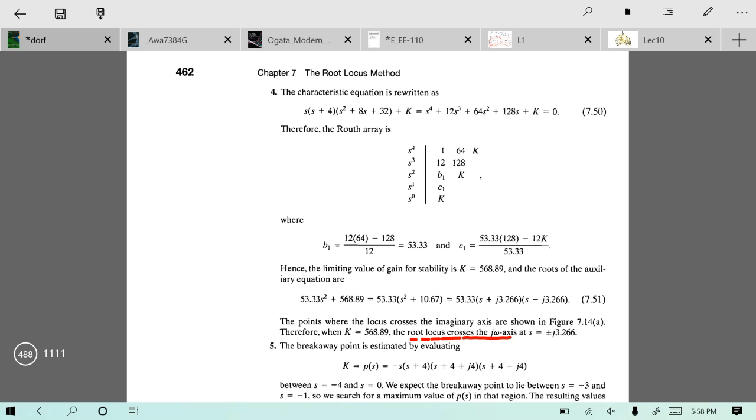However, if there is a zero over here, your system is marginally stable. So we can make use of this property. We would make an entry equal to zero, and then find the value of s when this entry is zero. That value of s would be the point where the system is marginally stable, and obviously at that point your poles will be crossing the j omega axis.